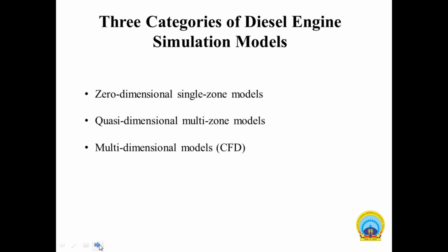That is the NOx formation submodel based on the Zeldovich scheme, developed by Zeldovich, the researcher. The soot formation submodel developed by Razleytsev, and the advanced NOx formation submodel based on the detailed kinetic mechanism (DKM) for correct prediction of NO emission in the engine.